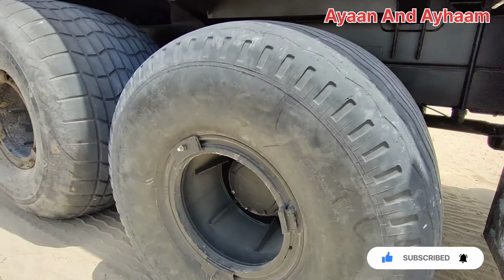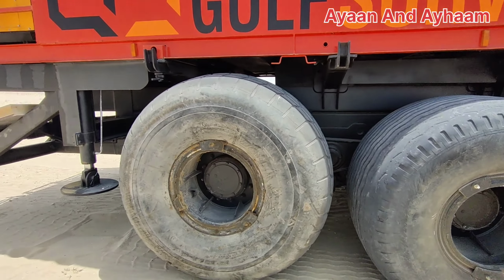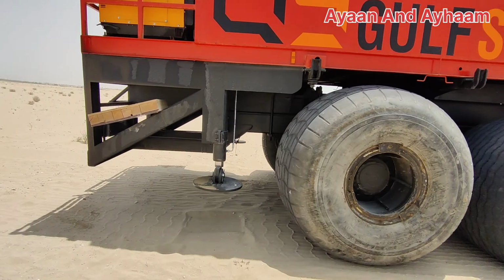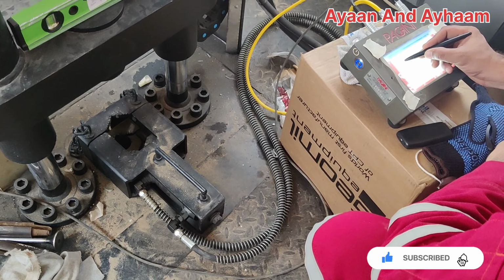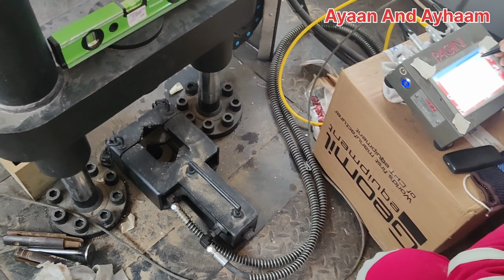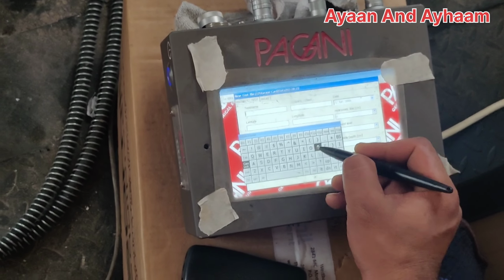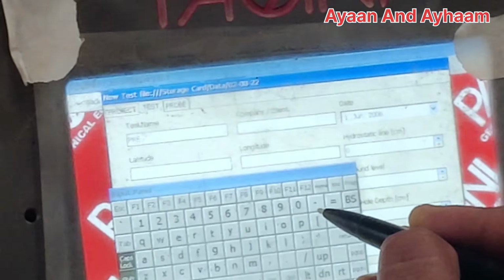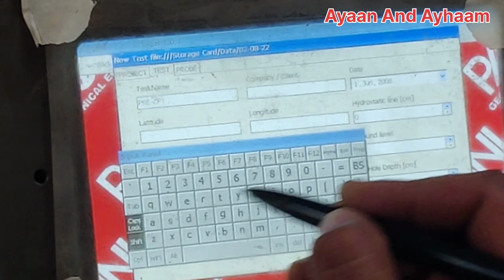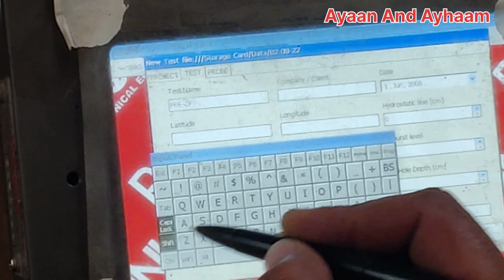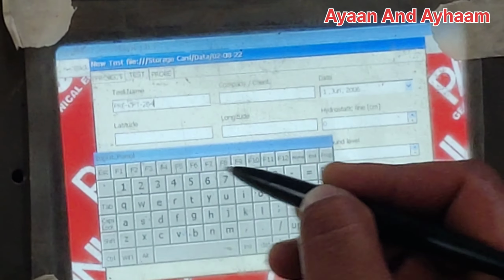First of all, survey setting out is required for the CPT location and point, the coordinates and the level of that point. Then orient or set out the CPT machine, this cabin which you have seen before, on the required CPT location. It should be as close as it can be, like 10 or 20 centimeters. The closer it is, the more accurate the result for the specific point.